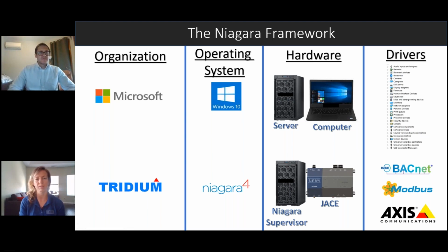So just to help clarify, BACnet, LON, Modbus, those are all protocols, and now we're shifting gears a bit to the overarching framework. So the Niagara Framework, it's really great at just bringing together all sorts of disparate protocols, so you can have a BACnet system with also some Modbus meters, you could have a trunk that's LonWorks, bringing all these different protocols together under the Niagara Framework.